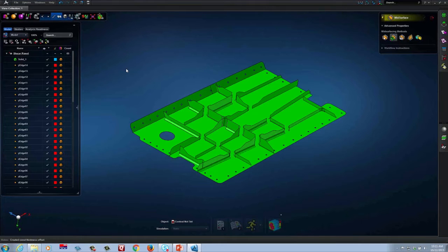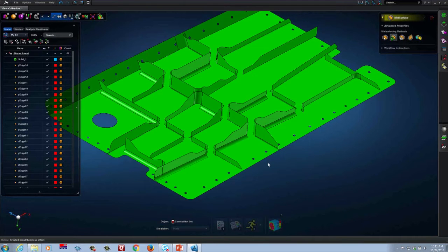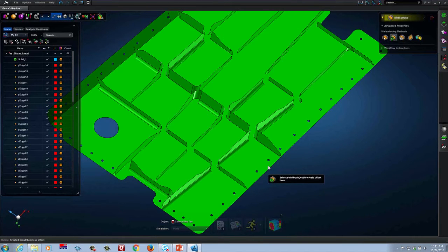If I actually look at what I get, though, with constant thickness, because this tool really was not designed to do this, I'm extending it beyond what it's really designed to do, I kind of end up with a mess. Honestly, using edge and vertex drag technology in MSC Apex, I could fix this, but there's a little bit of cleanup required here. I would like to do better, okay?